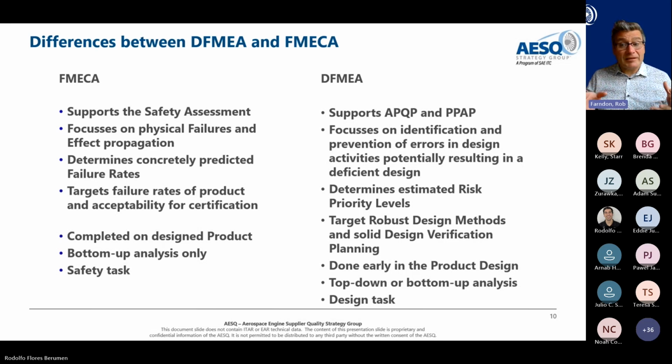I'm going to complete this analysis really on the designed product. You can do one early in the process, and that's fine. But the other thing is that it's a safety-led task rather than a design task. It takes different skills to the standard design engineer to do a FMECA. And it essentially is a bottom-up analysis where postulated failure mechanisms are traced up through the system architecture. And we have to evaluate not just the potential for the mechanism, but for the propagation.